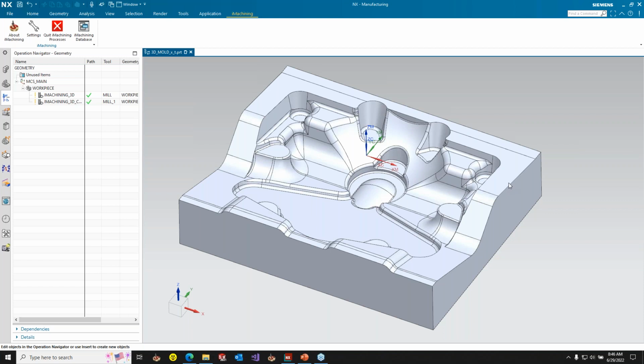For anybody that is cutting with iMachining, depending on the machine and the material and the tool, the ACPs really can do something magical. Being able to cut at the integer ACPs is the difference between vibration and beating up the tool, and it being so silent you can barely tell the machine is cutting. As I said, in iMachining 3D, we can limit the step up to never go below 1 ACP, because below 1 ACP really beats up the tool. That's the worst time for the tool.